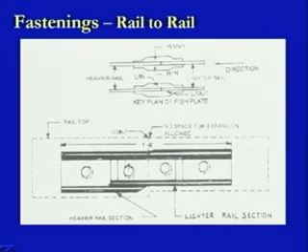Now, in this case we can see in the diagram a combination fish plate, where this is a bigger rail section, provided by a dotted line like this, and this is another section which is a lighter rail section, and both these sections have been jointed together. Now, in the normal conditions where one rail section is jointed with another rail section, a gap is allowed between those 2 rail sections, but in this case there is no gap being provided. So, it means they are butting each other.